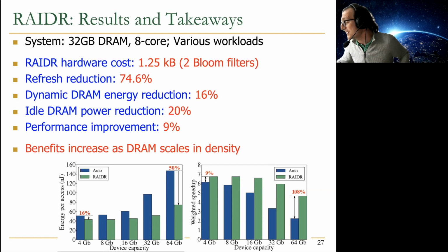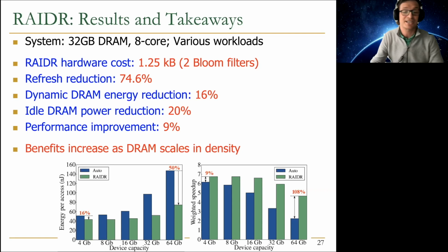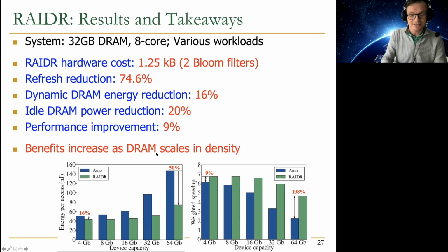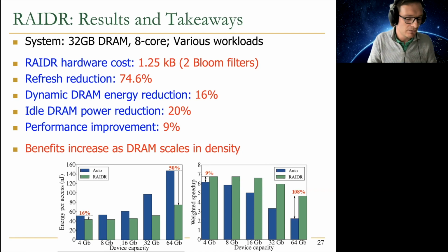Doesn't this also affect the lifetime of the cells? That's also a very good question, actually. It turns out lifetime in DRAM is not that problematic. In the future, we may have more problems with lifetime. But as far as we know, today we don't need to worry that much about the lifetime of the cells in DRAM. So it doesn't go bad that quickly. Now, nobody knows what the implications are 30 years down the road. So we need to think about the 30 years down the road. But within 5 or 6 years, it's not a huge problem, let's say.